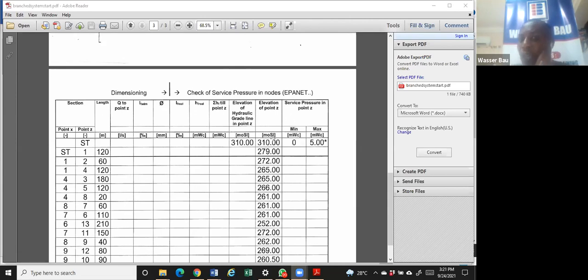The surveyor can also give you the elevation, because when you send the surveyor to site, part of his job is to get you the XY coordinates, which you use for your road design, which the surveyor will use for the road aspect. Then you, the infrastructure engineer, the water engineer, will now use the spot height, the elevation, to now do your own design. That's why in most infrastructure work, it is the road designer that goes in first. Oh, sorry, the surveyor goes in first.